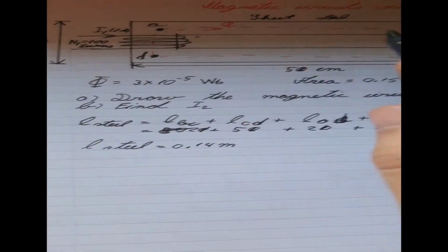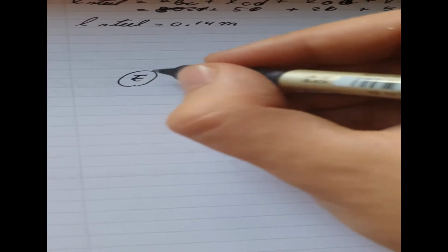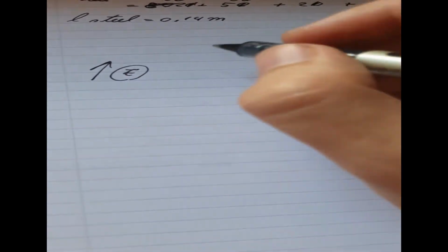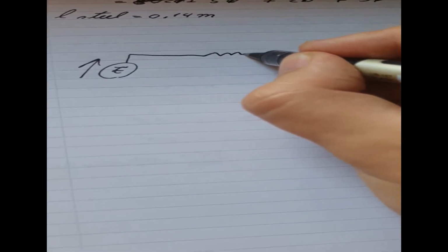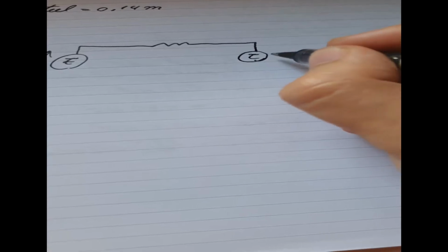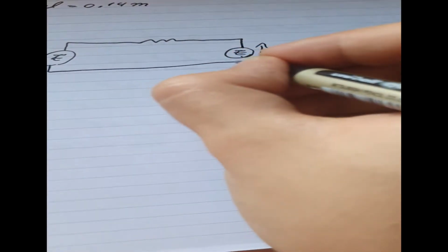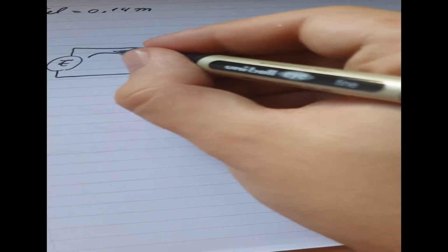We have two coils and only one material, so that will be pretty self-explanatory. Since the coils and the MMF are a replacement of the voltage source, we'll put one here. We'll put one resistor here as for the material. Then we'll put another one here under squiggly F. There you go. Then this is the direction of the flux, and this is the reluctance of steel.